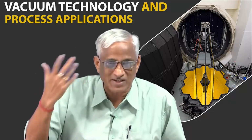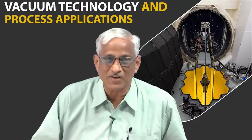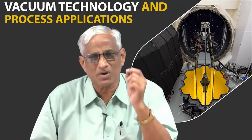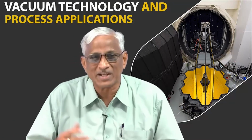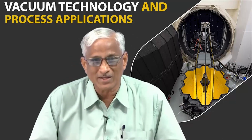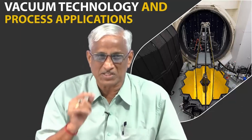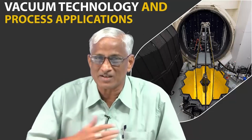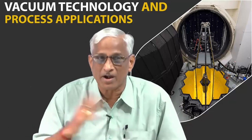There are standard procedures for it. Different companies have different capabilities and standards. Ultra high vacuum companies deal with outgassing in a totally different manner. Even a very small leak is not acceptable for them, but it is okay if the system is working at 10 torr. So, you should know when to neglect a problem and when to be very fussy about even very small problems, because I told you in earlier classes, even a few micrograms of gas can upset your vacuum level by one order.